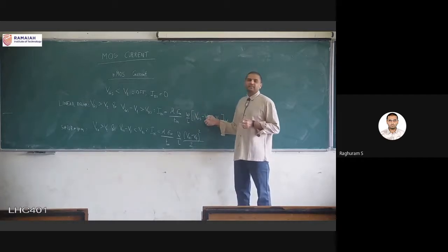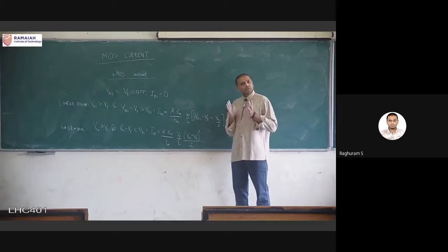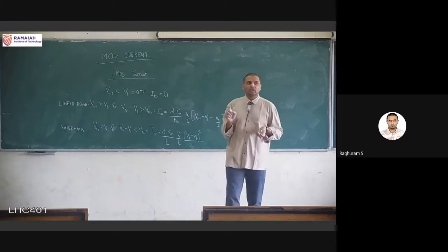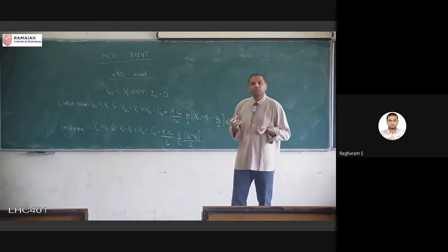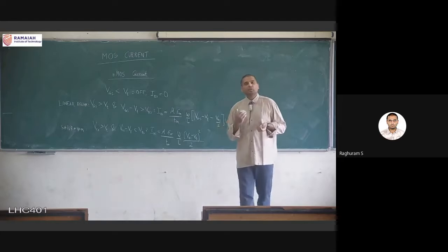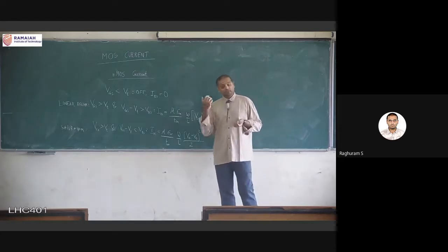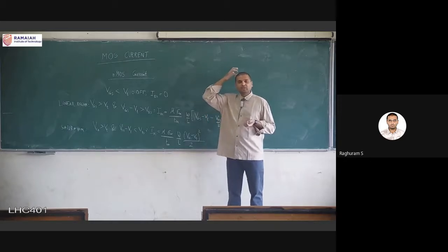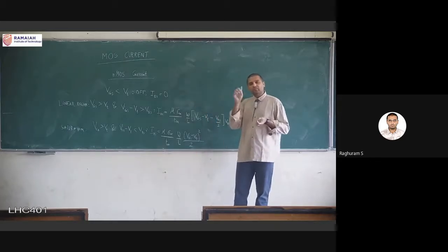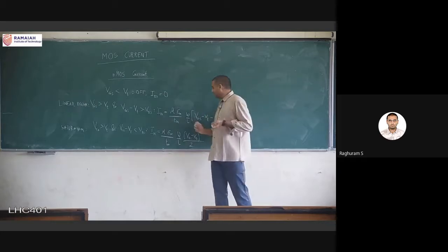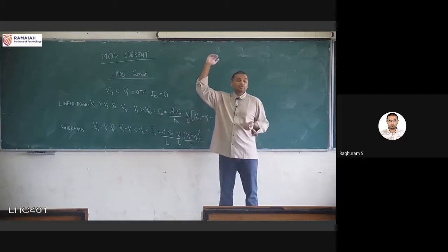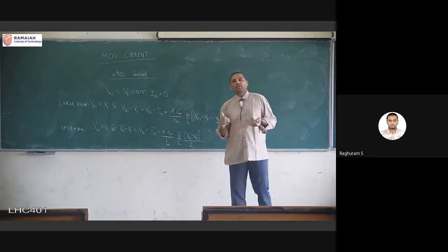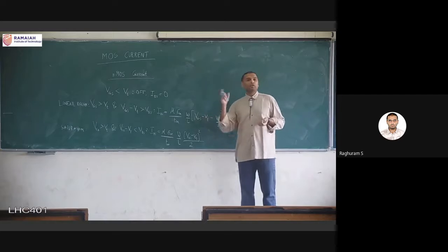Then VT. Again, there is not zero flexibility. There is some amount of flexibility in the threshold voltage. You can change it for some of the transistors to reduce it to a smaller value. People do that. Somewhere in the book, if you read, there is something called process corners. So some amount of flexibility is there, but that is reserved only for the very senior engineers. As a junior engineer, you're not allowed to touch that because this involves a lot of cost.